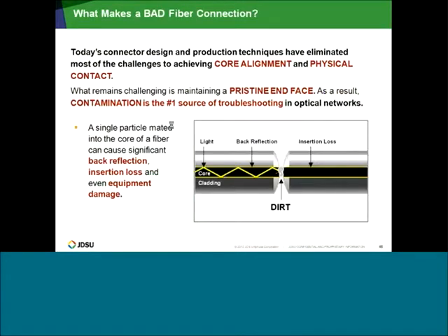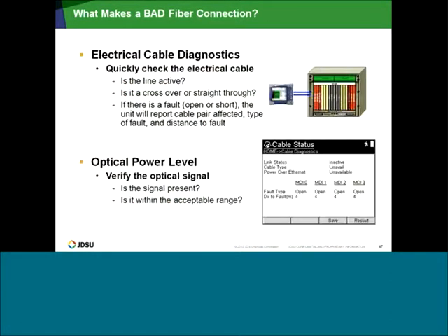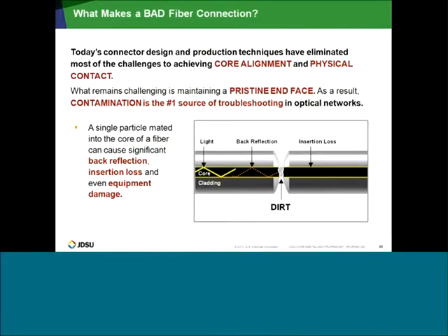Okay. Another thing that's extremely important for higher speed testing is making sure that you inspect before you connect. What happens is very bad. Dirt is actually the number one source of troubleshooting in optical networks. So it's very important to always inspect your fiber before connecting it.